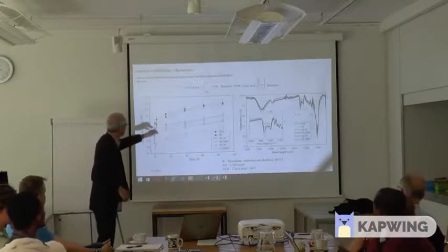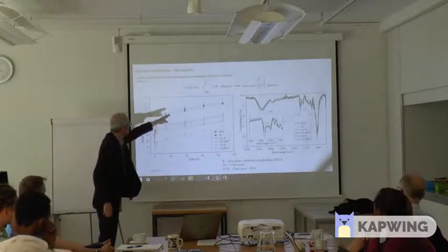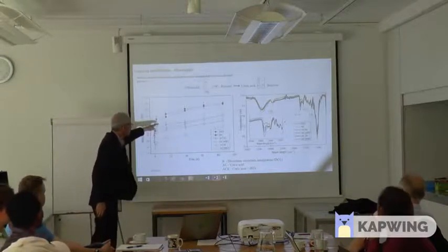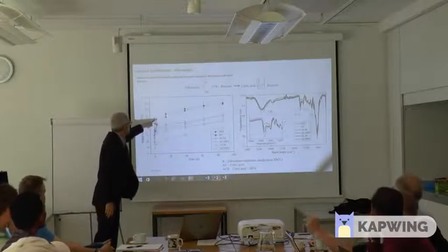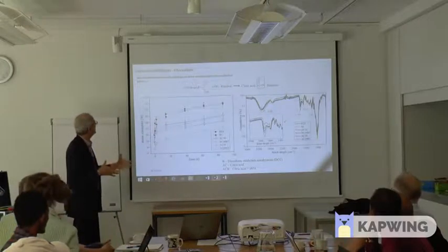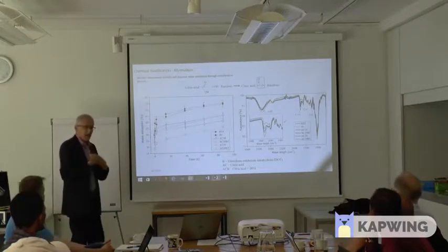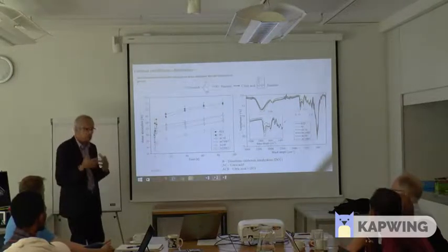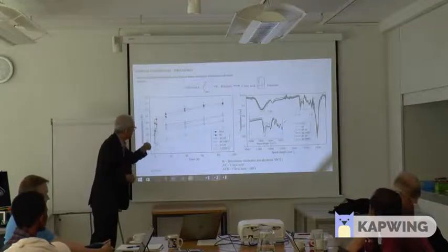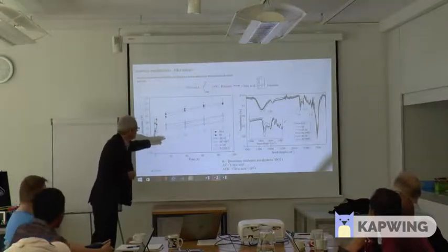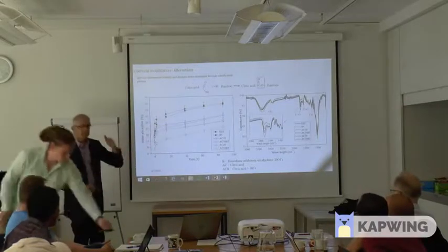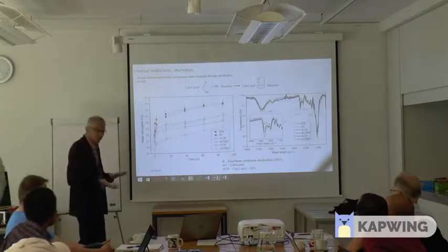In this particular case, the reference are the squares over there. If you just use the boron, you are almost the same. It's not avoiding any absorption of the water. The absorption of the water will be almost the same. But if we combine the citric acid with boron in that percentage, for example, you can have a considerable reduction of the water absorption.